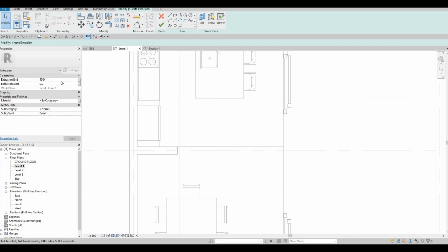I'm going to change this elevate extrusion end. Right now I'm just gonna put 600, but we could change that later on. Maybe we could just even put it at 400, and this will be stone. After that, there will be glass, and then after that the stone again.